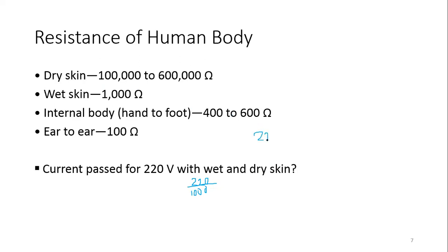This will be 220 divided by 100K, which is equal to 2.2 milliampere. So the current with wet skin is very large compared to the current with dry skin.